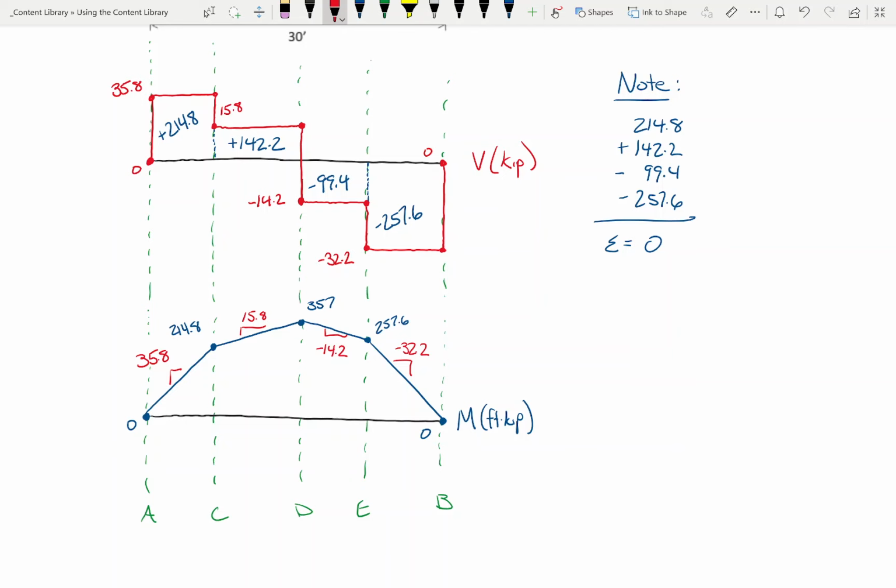Does anybody have any questions? So could you like interpolate from your moment diagram there and just find the moment about any arbitrary point? Yes, yes. So the question was like, what if I wanted to find the moment right here, right? Okay. So there are two ways of doing it. One way of doing it is to do what you said, interpolate. Okay. The other way of doing it is to cut a section and actually write the equations of equilibrium. You'll get the same answer.